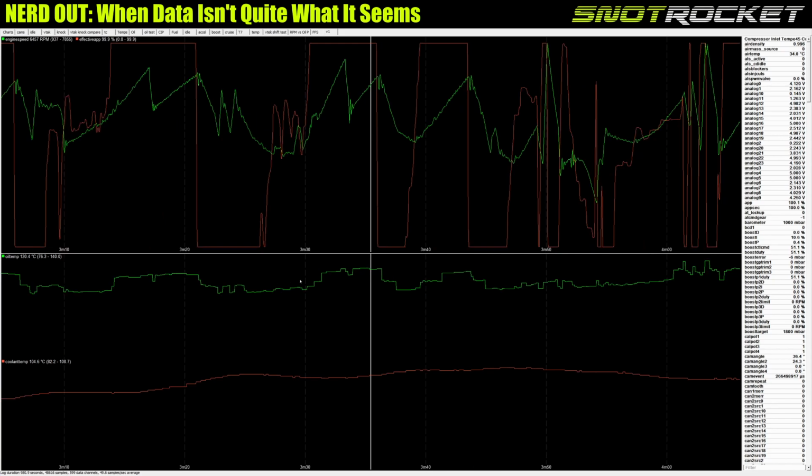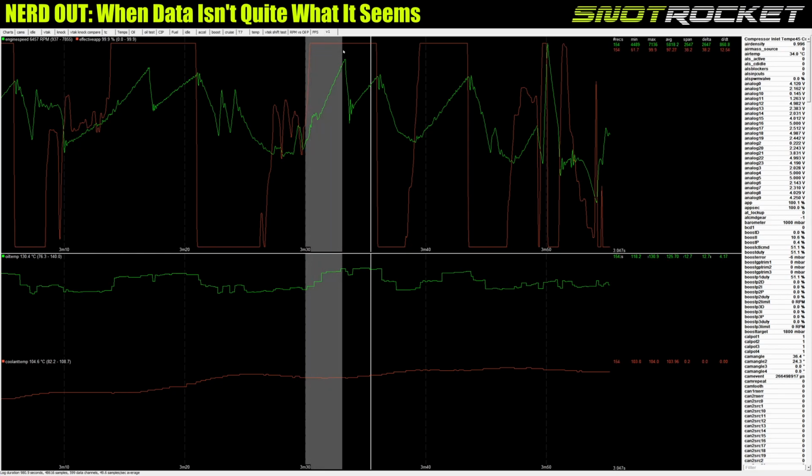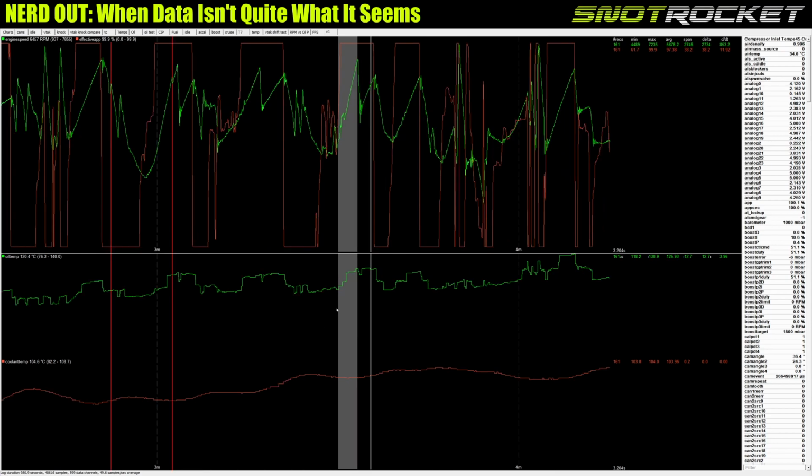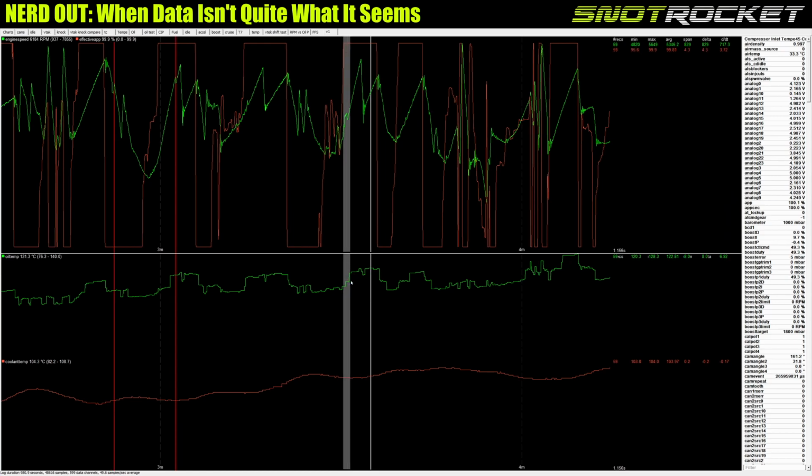And the oil temperature, if we look here from the point we go on the throttle, just in one gear, the oil temperature has changed from 118 degrees to 130, just in one quick gear, right? And that seems a bit excessive, but what's more important is the rate of change. So if I go here, there's the timer, so just in 1 second, that oil temperature has changed 8 degrees in 1 second. That just doesn't happen. Oil temperature doesn't change that quick.